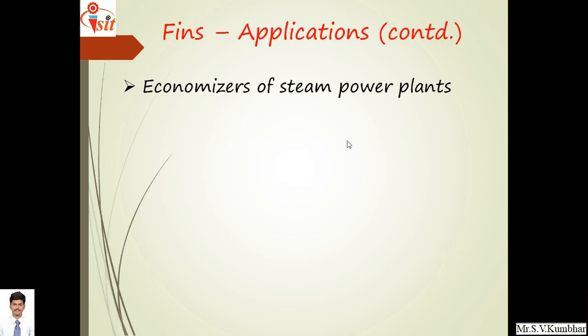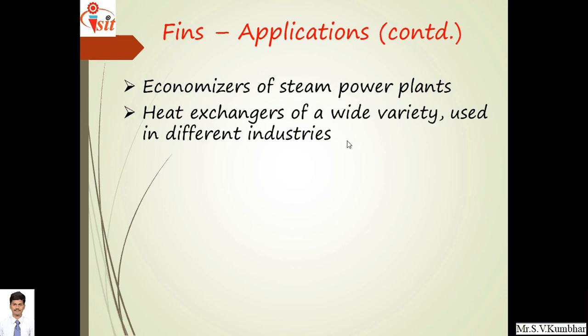Economizer of steam power plant. In an economizer, water is preheated with the help of flue gases, right? So water can be preheated with the help of fins which are provided to the economizer. Heat exchangers of wide variety are used in different industries.